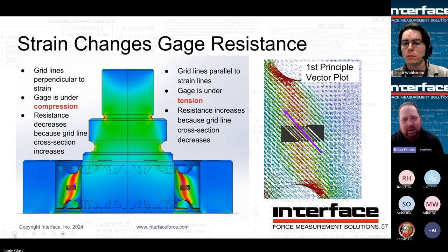The second thing I want to highlight here is if you go through some of our products, you're going to see that, as you saw earlier, our standard 1200 series has the female threaded hole in the top, right? If you look at this, you can see how the force applied at the end of that top section, which would be threaded, transfers all the way through the center portion out to the outer beams where the gauges are. So our 1200, 1100, or 1000 series will have a female threaded hole. We talked about the importance of mechanical mounting and the thread engagement and making sure you've got good tight connections and potentially even preloading. That is because it lends itself to much better consistency of how that load propagates through to the bridge.